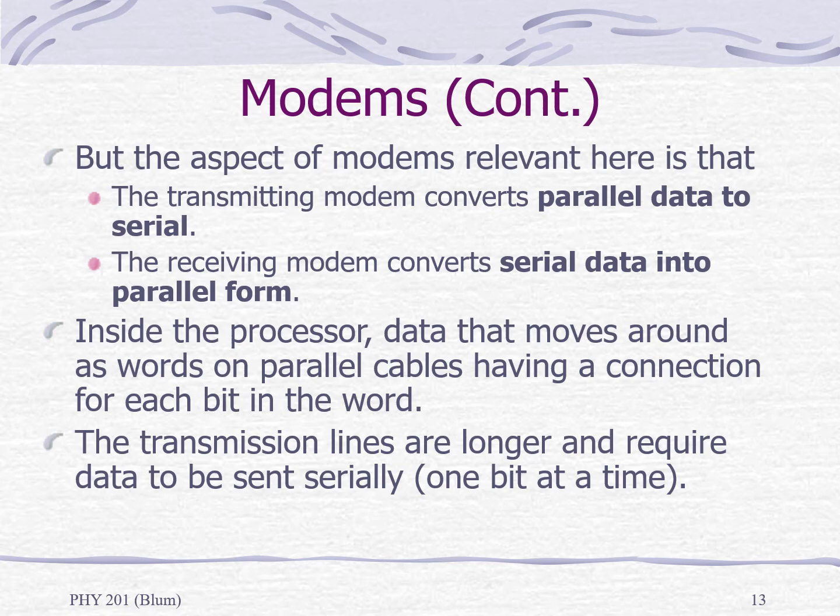And the job of the shift register isn't so much converting digital data into pseudo-analog data as it is converting parallel data to serial data, and the reverse, converting serial data into parallel data. This is another thing that a modem has to do. So inside, say, a processor, data moves around as words in parallel.